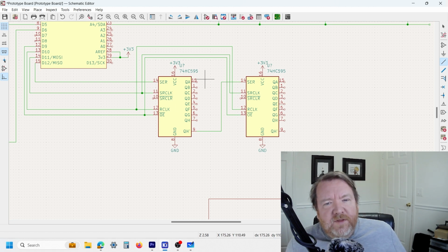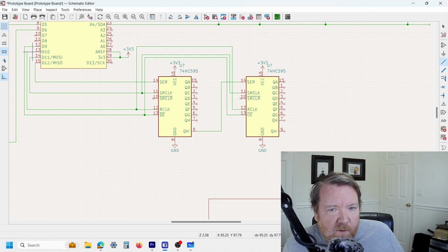So in some respects, you can think of this as a very simplified version of the I2C interface. It's not using encoded packets, but basically it's encoding data on a serial line with a clock pulse to control outputs. Okay, so that's pretty much what it does. I'm going to switch over in a minute to show you a demonstration on a prototype board, but I'm actually going to be building a project based around this and the Arduino, and maybe up to 10 7-segment displays.